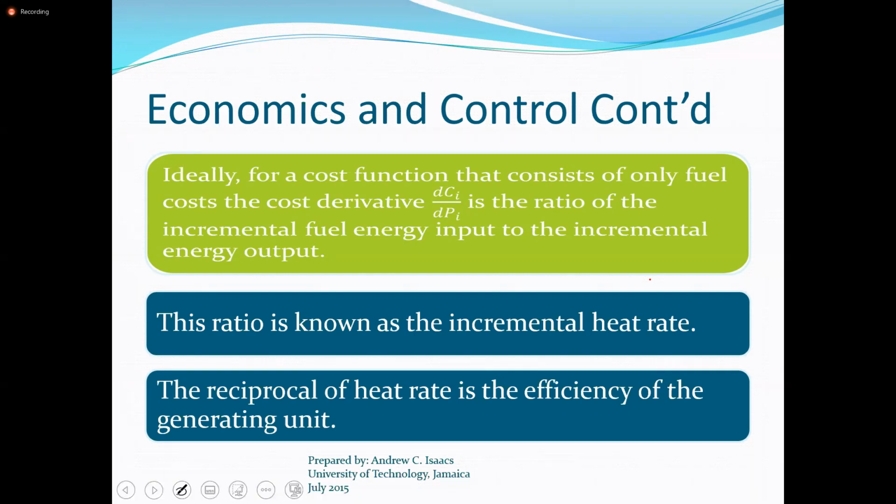Now on the fuel, you'll see fuel and IPP. Now it is true that whatever the cost of production of providing the energy, we as customers will have to pay for it. But to balance that out, the OUR will require of the utility and producers that they operate at a certain heat rate. So the efficiency with which they convert that BTU into electrical power is now important.